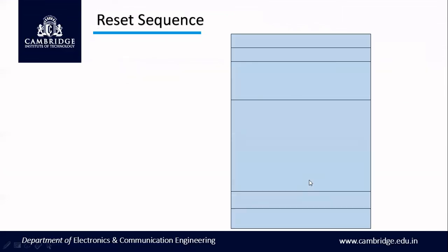So if you have to explain the reset sequence, say you are starting at this address. This is the memory. This refers to the address, and this refers to the data there. So inside this table, at this location, I should have the value of my stack pointer, right? If I need to initialize the stack pointer value, I should be very clear about what stack area I'm going to use in the program.